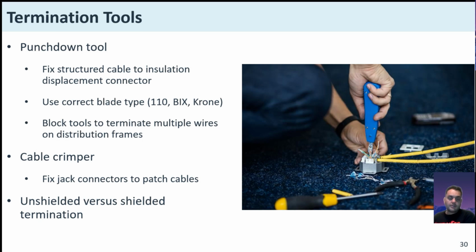for shielded and screened cable, termination must be made to shielded IDCs or modular plugs. On an IDC, a metal clip is placed over the exposed foil or braided shield and bonds the cable to the housing. A shielded modular plug has a metal housing and is not terminated using a standard crimper. There are several different designs for crimpers, but all follow the principle of connecting the shield cable to a bonding strip. I'm not sure if they show you crimpers.